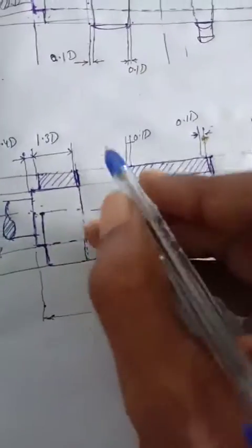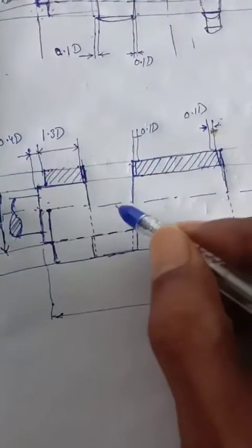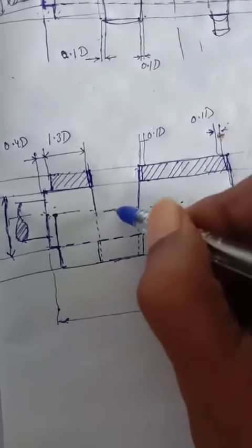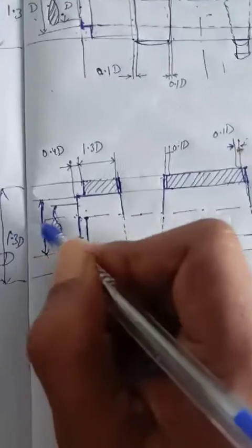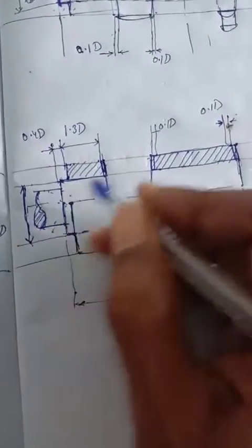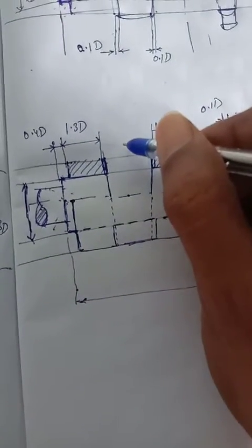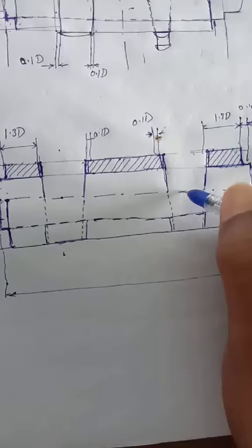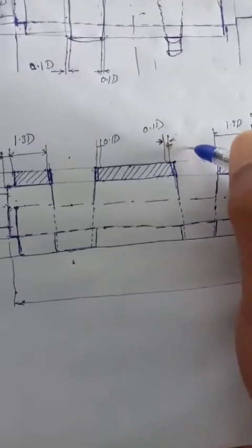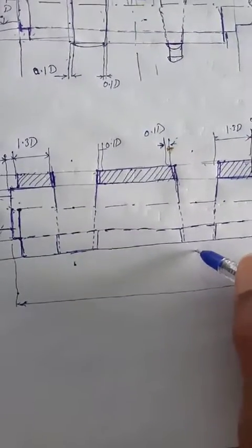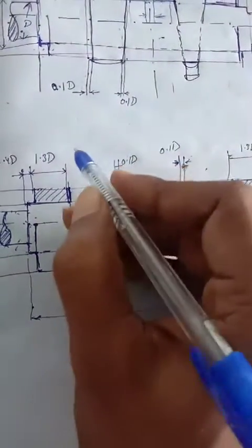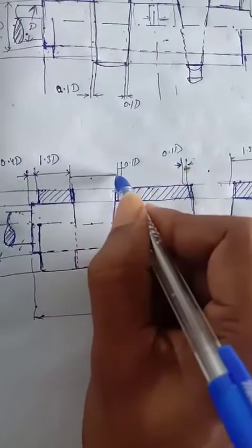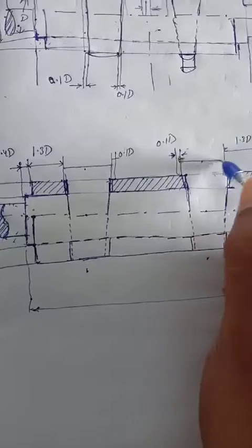Okay, so this is the setup, and now we are going to fix this sleeve into these two parts. Okay, so look at this, how to fix this one. Take this distance as 4 into D. Calculate 4 into D, that is coming from 20 diameter. So 4 into D is 80. So you can take here to here distance 40 and here to here distance 40. And similarly, this point you can take as the center point, and here to here 40 and here to here 40.